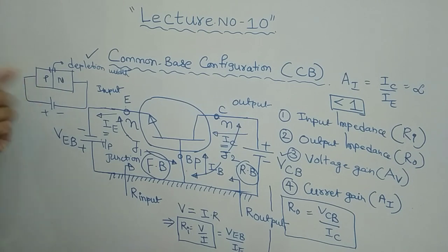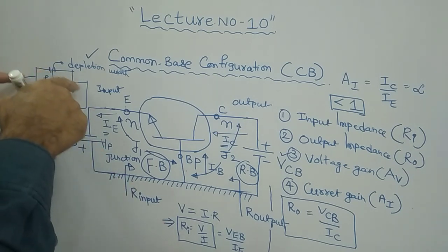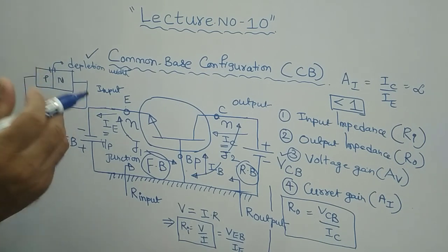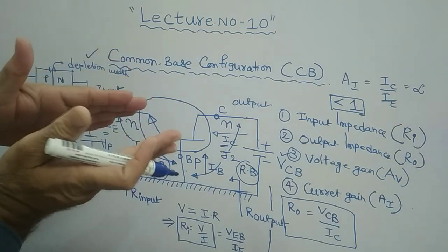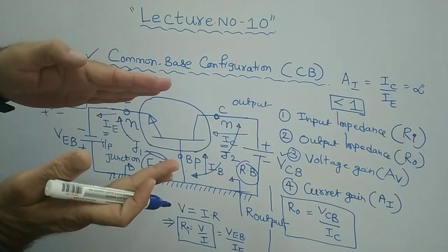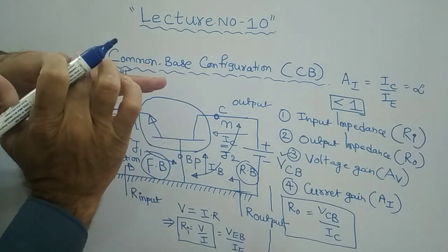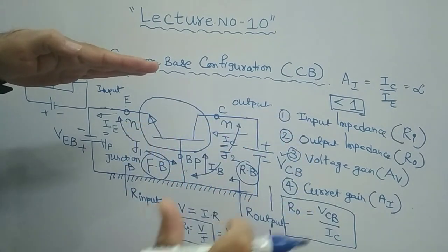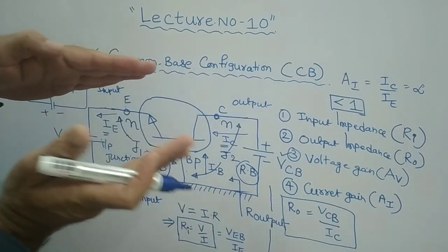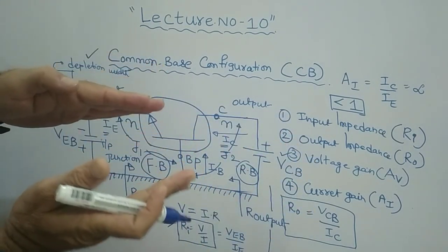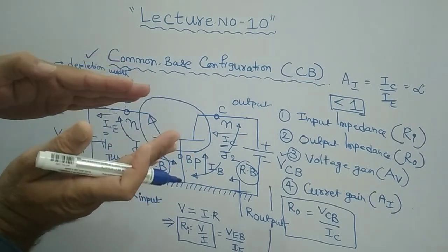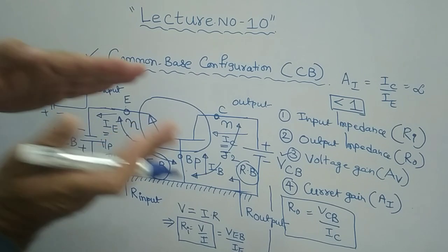Thereby, for these two plates we are giving some external voltage. So these two plates will act as parallel plates. This is one plate, this is another plate: P-type material, N-type material. These two plates are connected with an external power supply. Then this is called the capacitive effect. It is a parallel plate capacitor. So the PN diode works as a parallel plate capacitor.